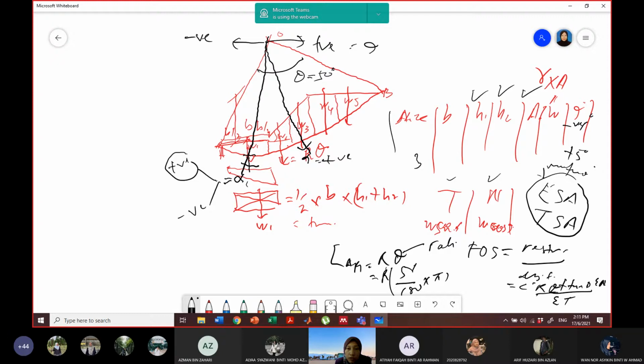So again, how do you ensure that your slope design is safe? You will know that by having the final answer FOS. If you have FOS equal to 1 or more than 1, we can say that the slope is stable. This is vice versa: if you have FOS less than 1, then this is an unstable slope. So that is the recap of the previous topics.